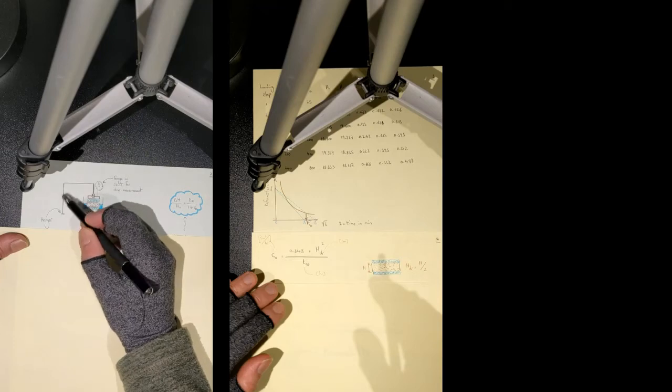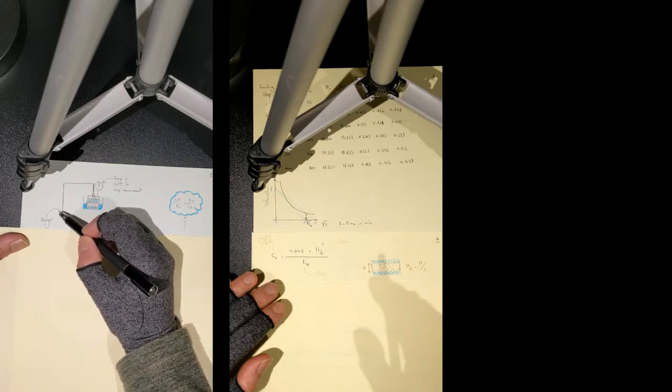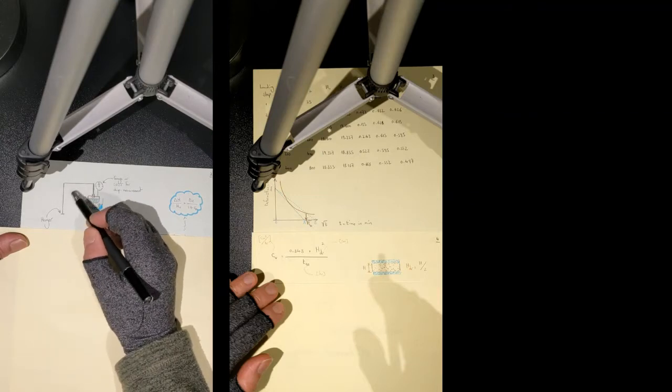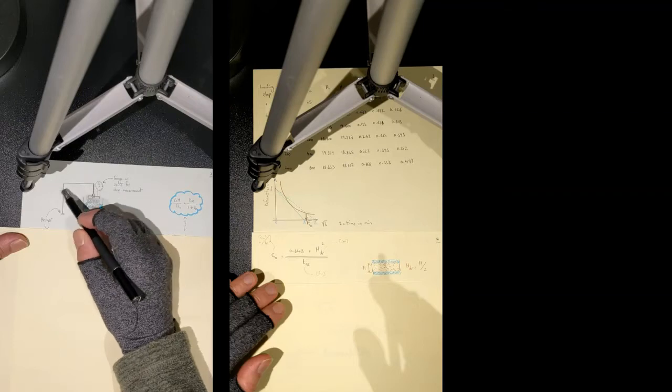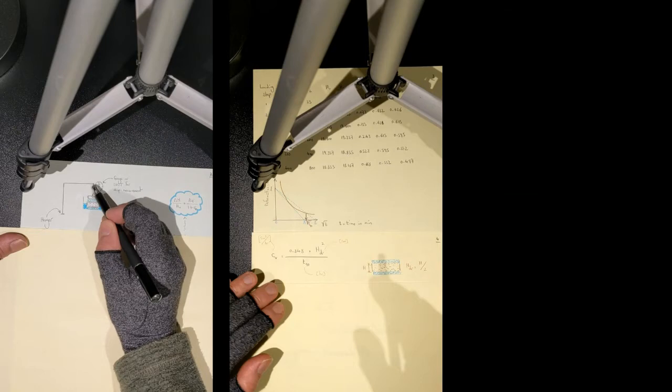And on this hanger, you can put different weights, different values of dead weight. By putting these dead weights on the hanger, the dead weight will be multiplied by a number, which depends on the length of your lever, and applies axially and vertically to your soil sample.